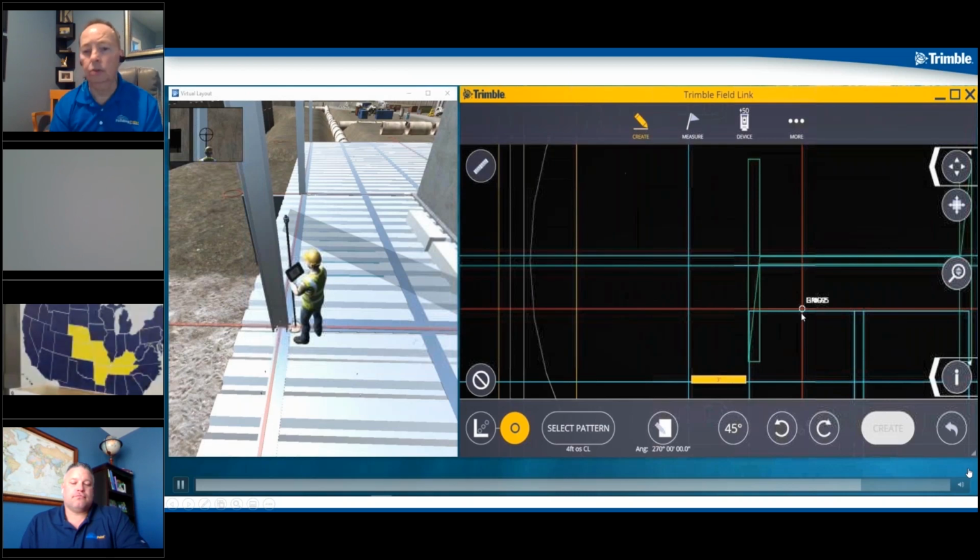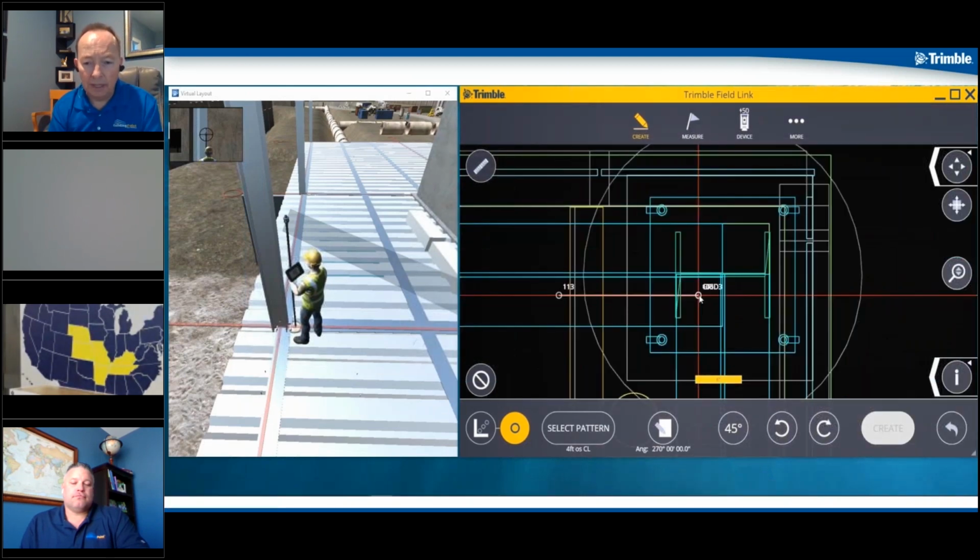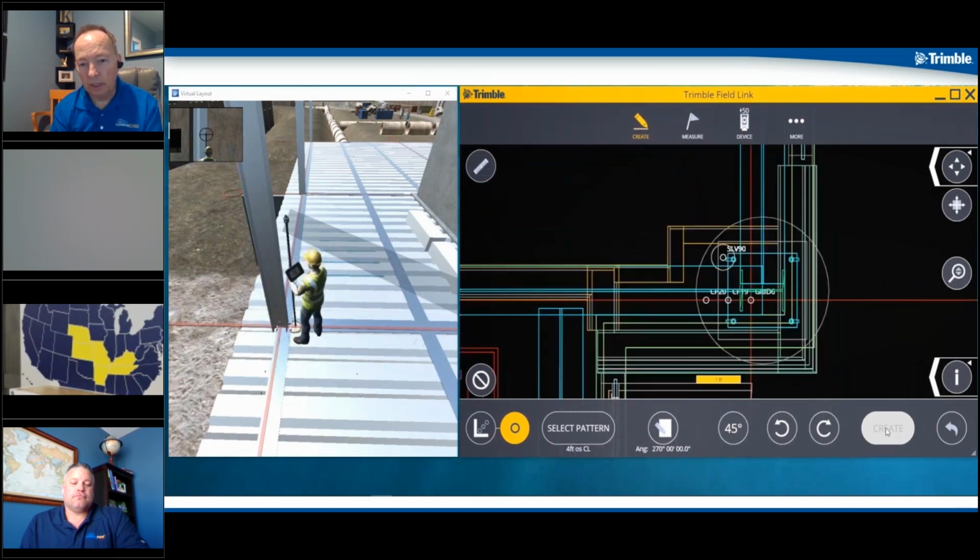And again, if you put underscores in front, when we hit that layer tab over there on the right, it's going to pop all of the layers they're most interested in to the top, so that they can find their stuff quickly without going through the other 98 layers that were brought in by Revit or AutoCAD or whatever software authoring tool you're using.